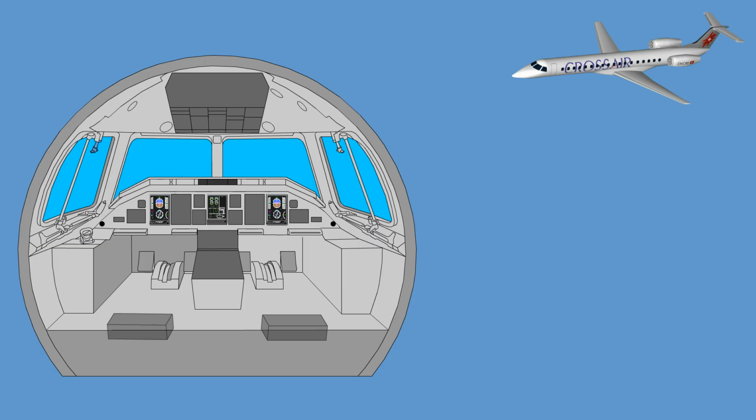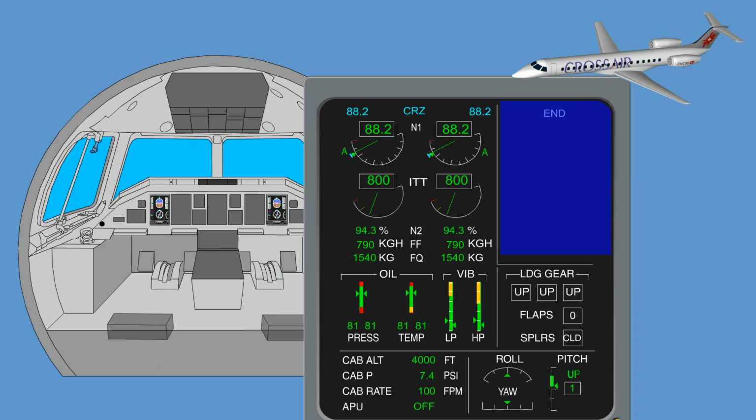In addition to the indications on the primary flight display, there are also Autoflight-related messages on the engine indicating and crew alerting system display. Whenever the autopilot fails, a red autopilot fail warning message will be seen. An amber autopilot caution message indicates that the autopilot had a power-up failure.